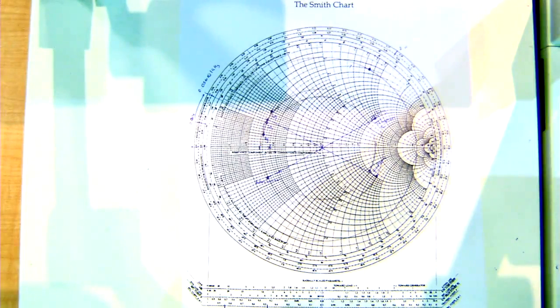So these problems become much more challenging because now you've got to match over 50, 100 megahertz, a gigahertz, multiple gigahertz. Generally, what you do in this type of design is try to match in the middle of the band and hope it's not that bad at the edges.